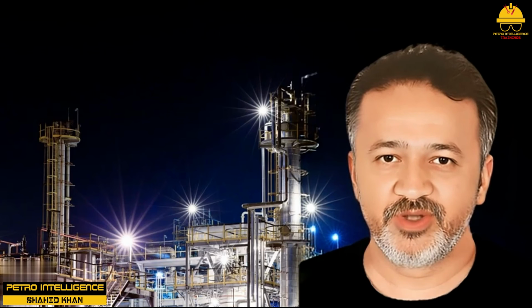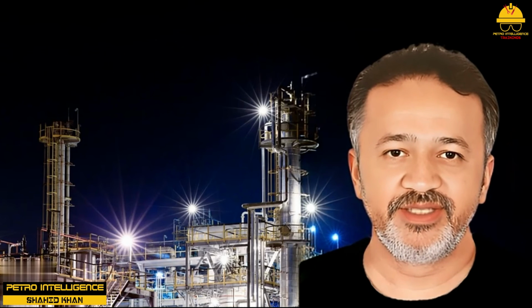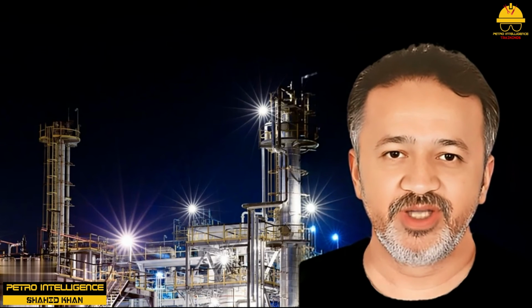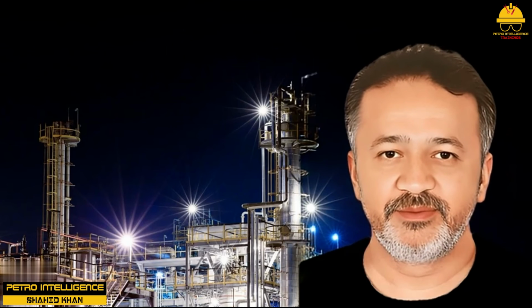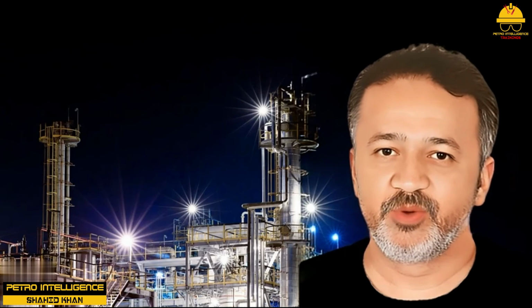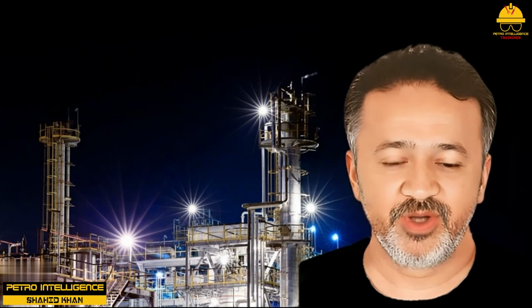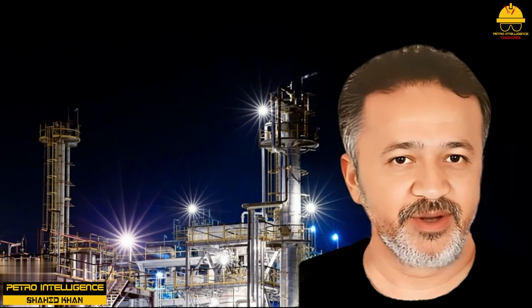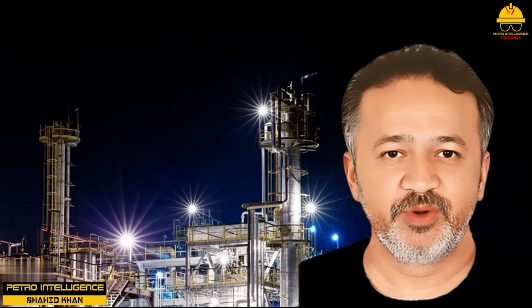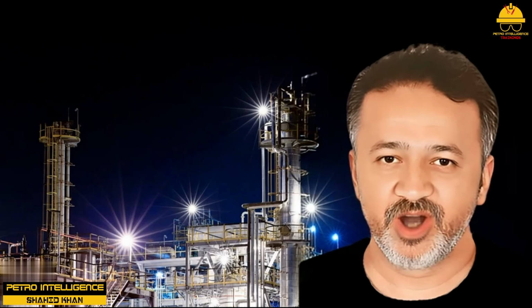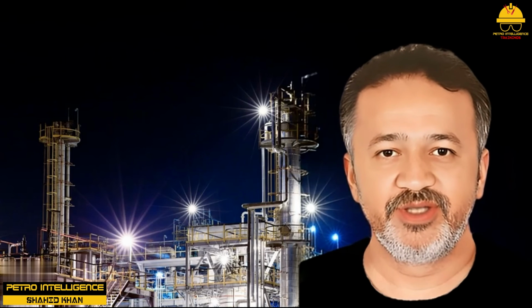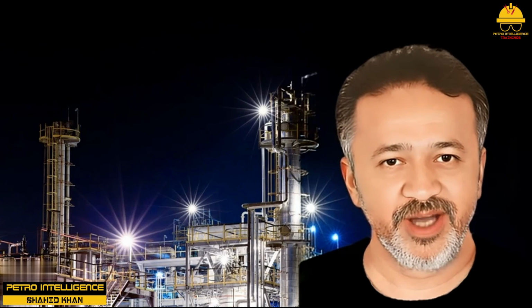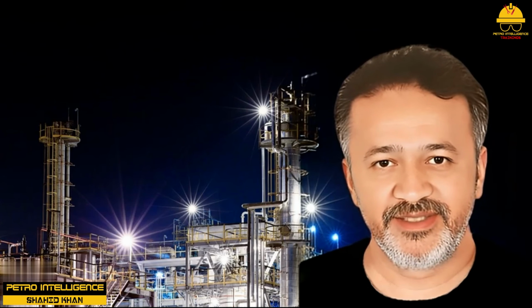Usually, any reactor or reaction system can have a set of conditions that could cause a hazardous situation if allowed to exist. Safety devices such as high-pressure relief valves and alarms, high-temperature alarms and emergency cooling, fire control systems, and toxic chemical detection systems are available for most hazardous conditions and should be installed as needed. The choice of the method for heating or cooling the reactor must be made in the design phase.